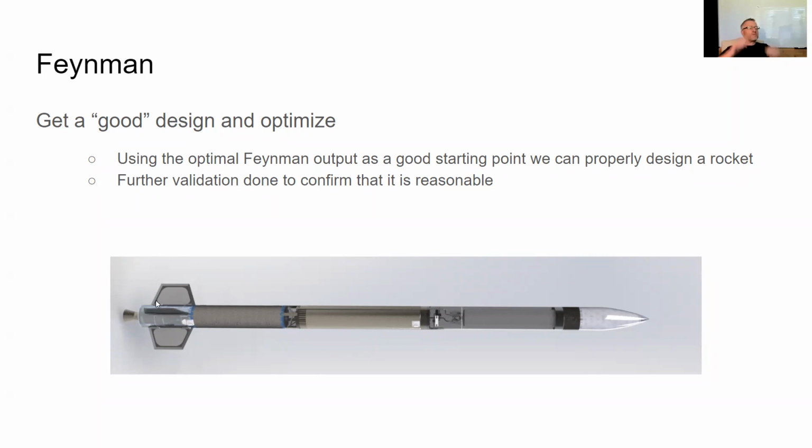I was actually wondering about your tanks. Is it just solid carbon fiber, or do you layer it? It's just solid carbon fiber. We use a pre-preg carbon fiber, which means the epoxy is already in it in the optimal strength to mass ratio.